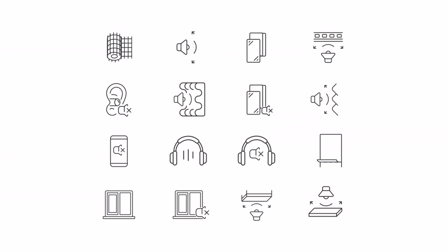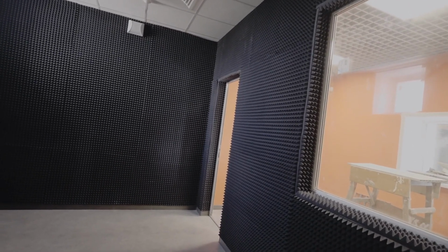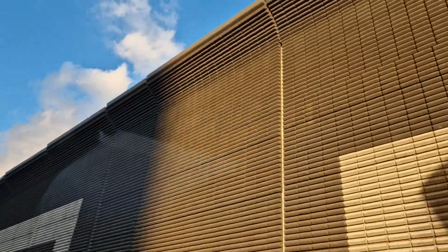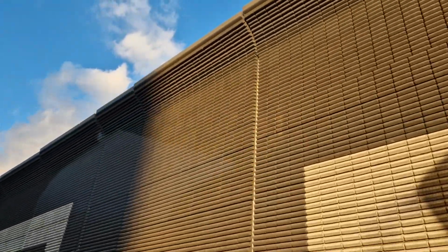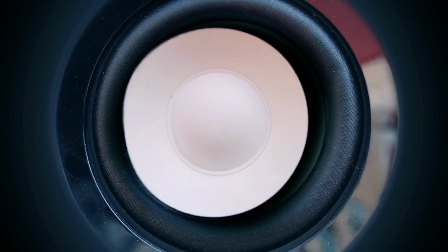Key soundproofing materials. Several materials are commonly used for effective soundproofing. Mass-loaded vinyl, MLV, is a dense material that adds mass to walls and ceilings. Multiple layers of drywall can also be used, especially when combined with Green Glue, a sound-damping compound that further reduces sound transmission. Other options include using resilient channels and isolation clips to decouple drywall from the studs, minimizing vibration transfer.